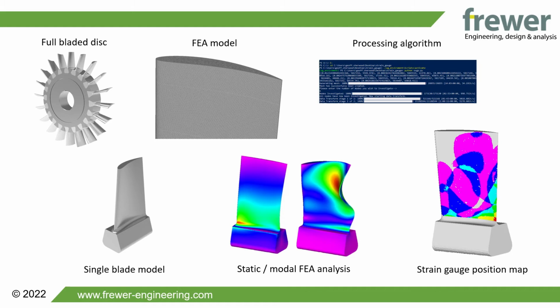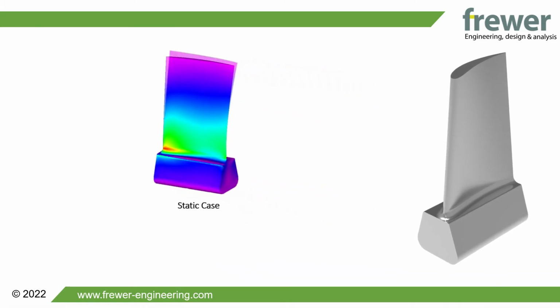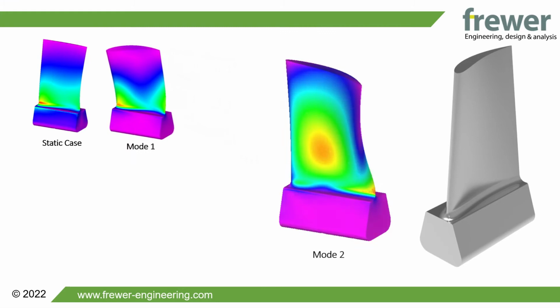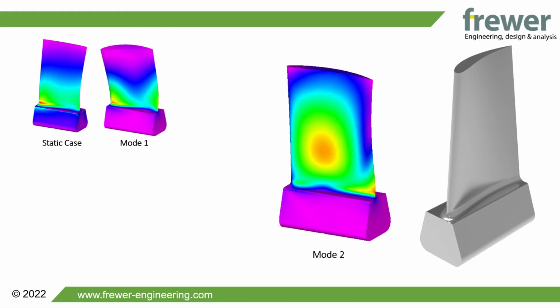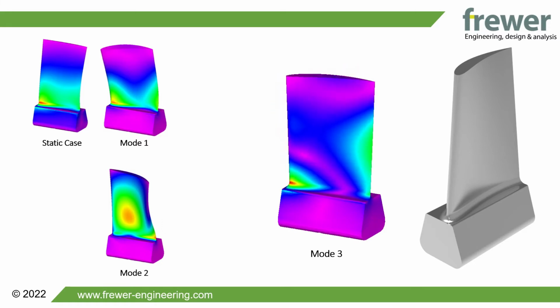Finite element analysis models are used during design to identify and resolve any issues early on. These models must consider both the radial forces due to rotational speed and any vibrational modes which may be excited during operation. First, a static analysis is conducted at the maximum operating speed to predict the deformed shape and induced stresses. Next, modal analyses are conducted, one for the undeformed or zero speed shape and one for the deformed maximum operating speed case. The changes in blade geometry and temperature under load affect the natural frequencies and must be captured in order to create representative Campbell diagrams and identify any problematic operating speeds.